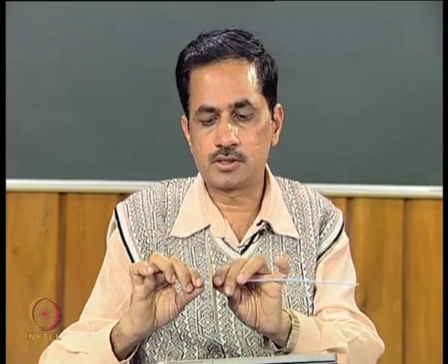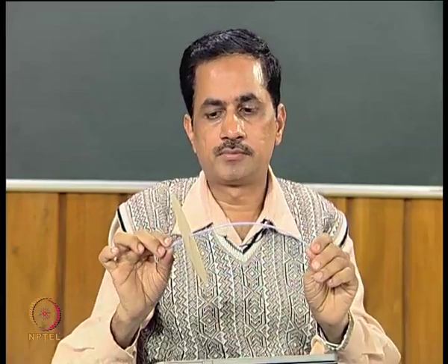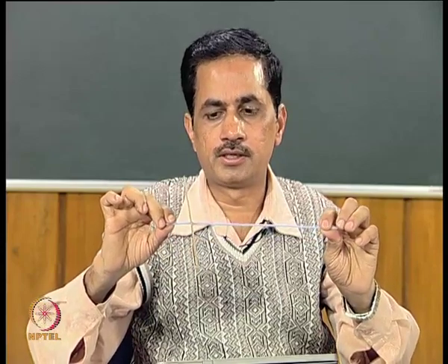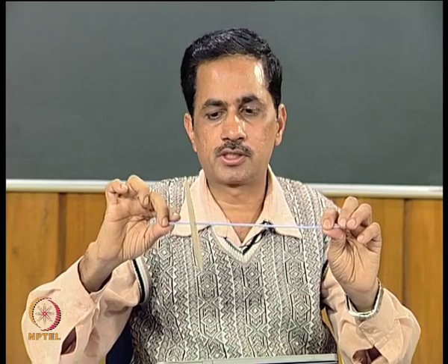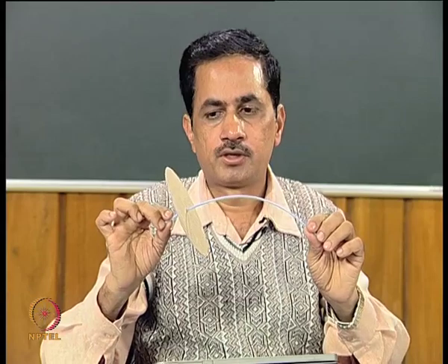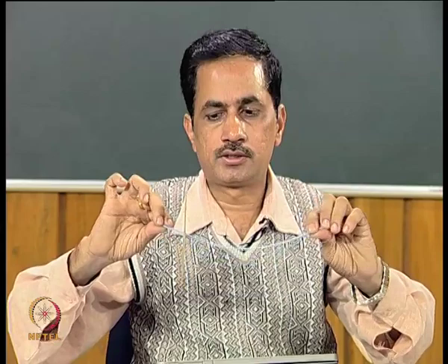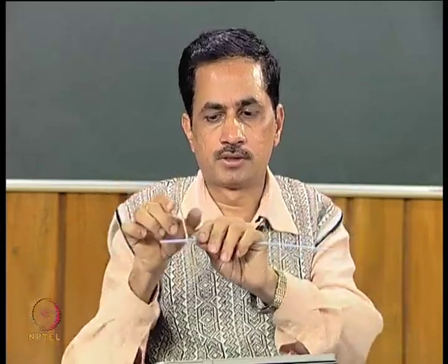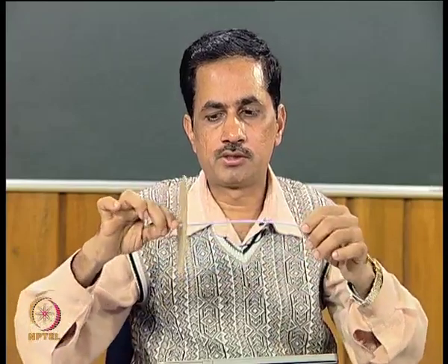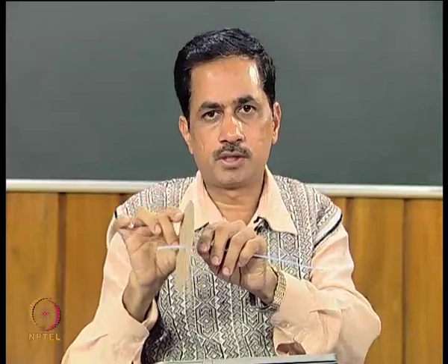But if the same disc is at an offset, not at the center, now you will see that when it is at the equilibrium, the disc will be vertical, but when the shaft is wobbling, the disc tilts. You can see during whirling it tilts about its diameter, and this particular motion is taking place in two planes. So continuous wobbling of this particular disc will take place.